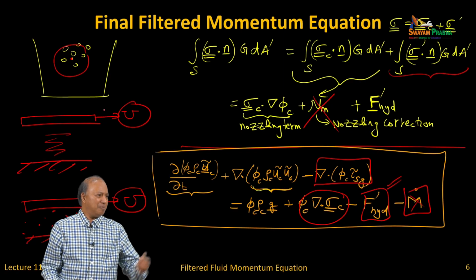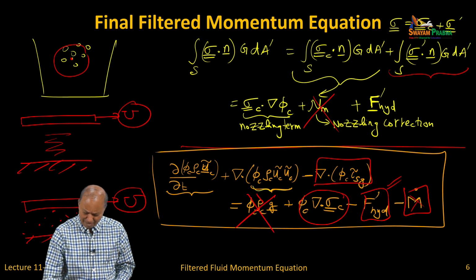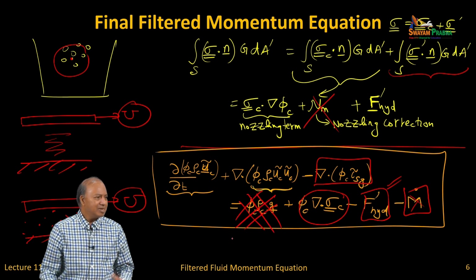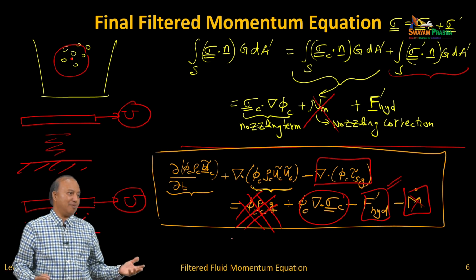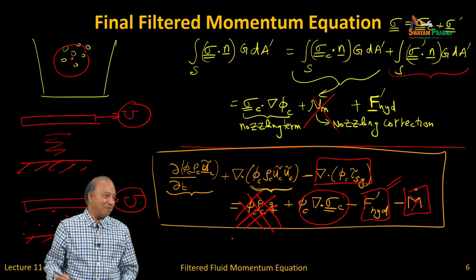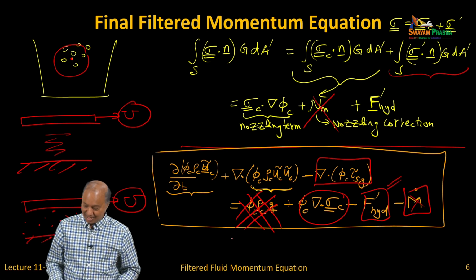This viscosity change will be a thermodynamic and transport effect. If you have a high speed flow like a rocket, you will just happily throw this term out, because its gravity effect is negligible as it is going at high speed. Whereas someone doing a sedimentation problem, this is the main thing.